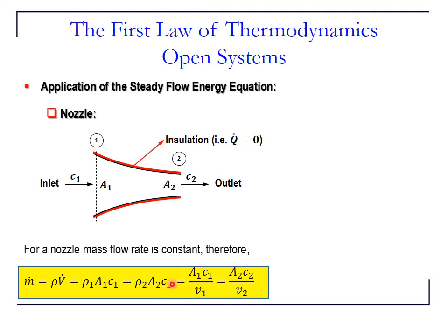So they are inverse to each other. Okay. So in this module, actually we use specific volume more often than density. Okay. So these two, I would say these two are most common, most often used when we calculate the mass flow rate. For example, when the mass flow rate is given, and C2 is given, V2 is given, and then we'll be able to calculate the cross-sectional area at the outlet.